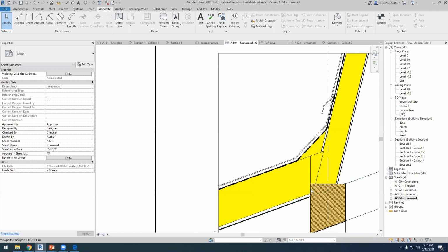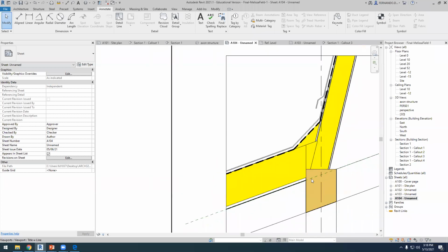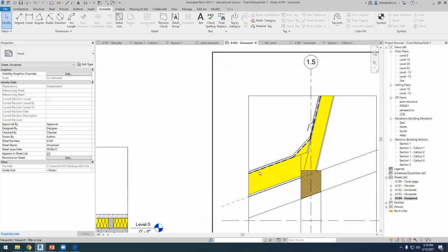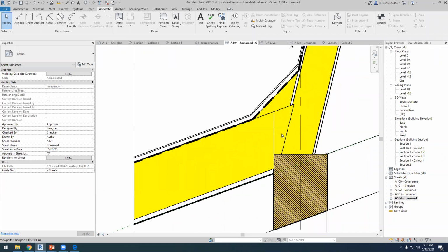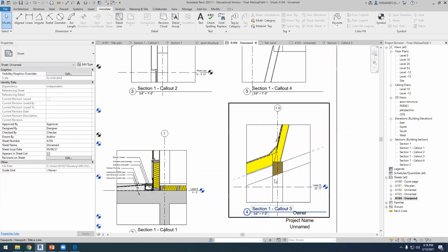We need a structural element on which this wall is resting, and that's all we need from the structural point of view. And then we just need to continue the thermal insulation. We don't have to interrupt the thermal insulation, and we don't have to interrupt the waterproof layer here. And then we have this zinc protecting the waterproof layer. There is no secret to these kinds of details.